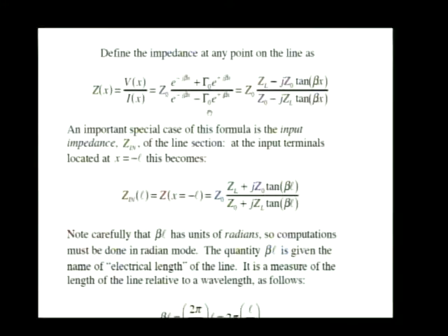Okay, this is a formula for the ratio of total voltage to total current at any point on the line. This is what I was talking about earlier when I said that you're giving that piece of transmission line to the tech and telling him it's a 50 ohm line and he's wondering what you mean by 50 ohms. And I said, you can't even say to him that if he measured the ratio of the voltage to the current at any point on the line, he'd get 50 ohms. No. If he measured the voltage to current ratio at any point on the line, V divided by I, it changes depending on exactly where he makes the measurement. What location on the line.